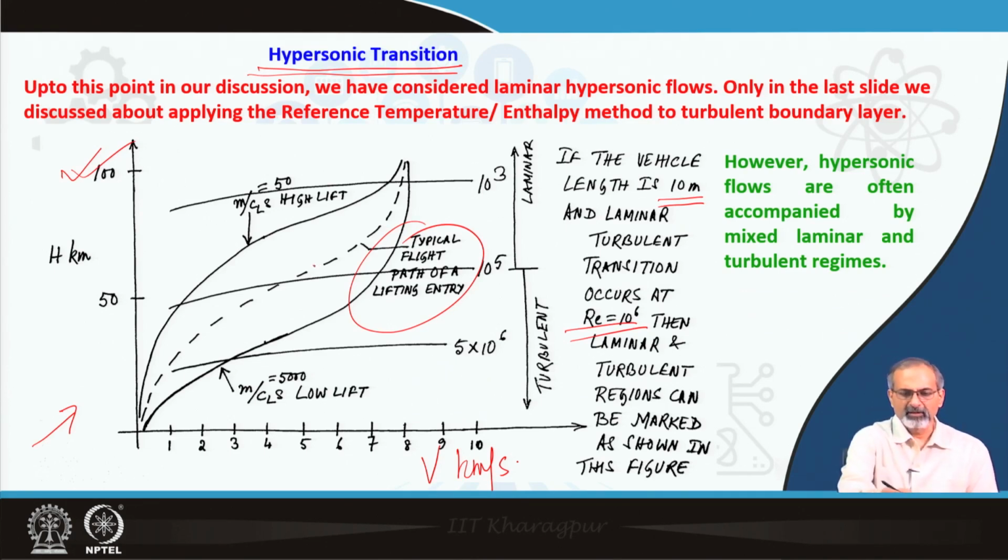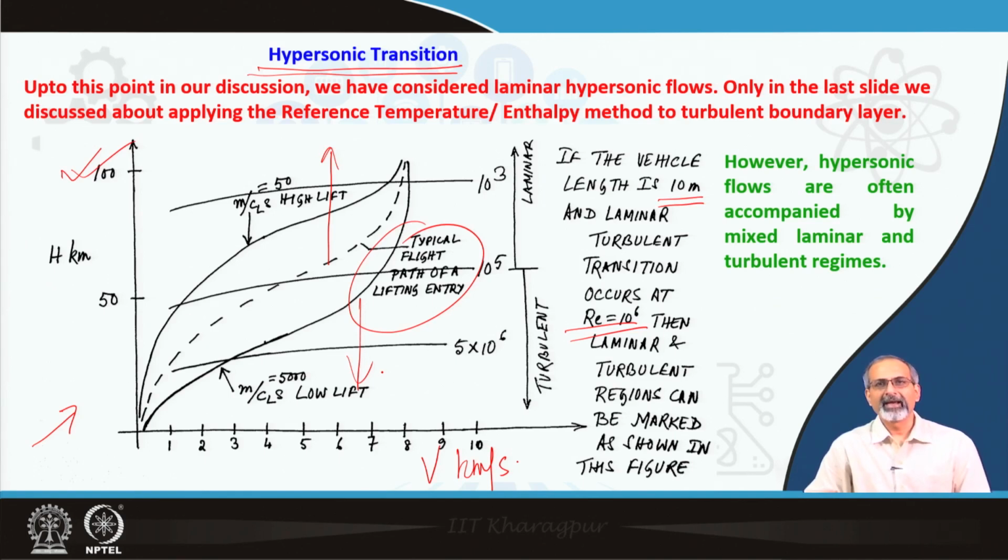At these kind of altitudes, it may go through purely laminar flow, while at lower altitudes, it is likely to see a lot more turbulent flow developing on it. And then transition from laminar to turbulent flow makes a lot of difference in the sense that the skin friction coefficient and the heat transfer coefficients are dramatically increased if the flow becomes turbulent, and therefore predicting the point at which the transition onsets or the region over which it onsets is always a big question.